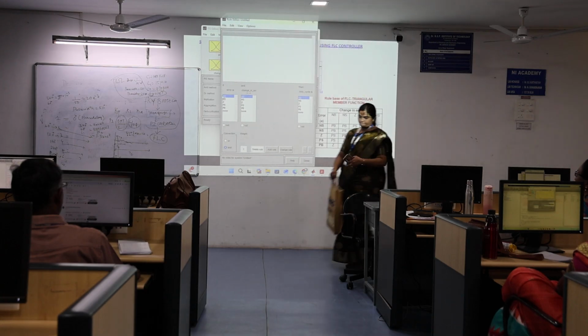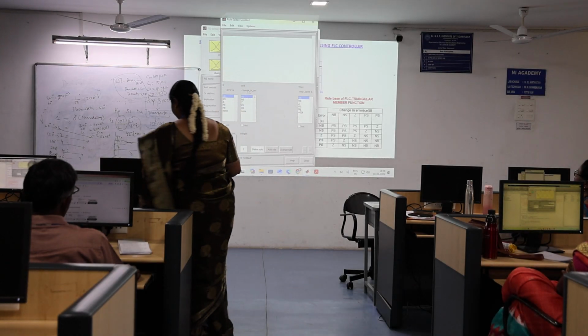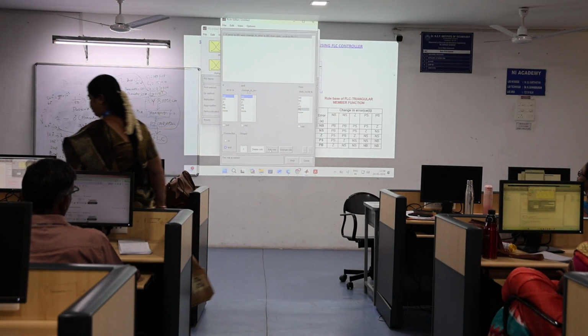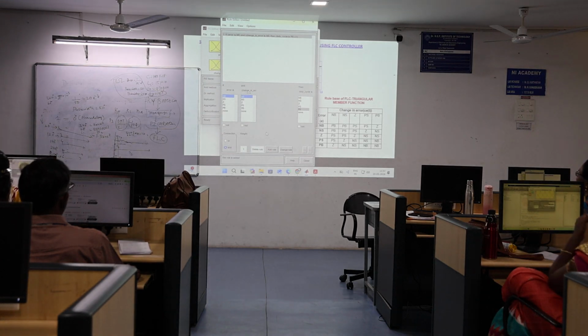So error is negative big. Change in error is negative big, my value is positive big. Add rule. Okay, then here AND OR connection is there. I have written only the AND variable, not OR. So connection you can choose AND, OR and all. Not is also there. Okay, and the next one is negative big.